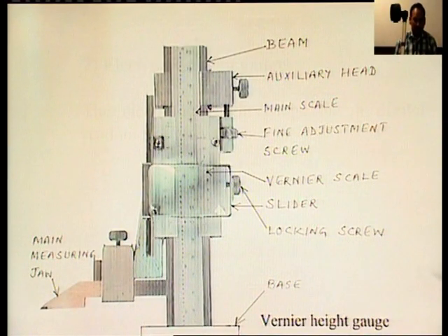measurements should be performed on the surface plate. The beam of the height gauge should be clear and free from dust. Springing of the measuring jaw should always be avoided. Final setting of the vernier height gauge should be made after the slider has been locked to the column, and the height gauge should be tested for straightness, squareness and parallelism of the beam, measuring jaw and scriber surfaces.